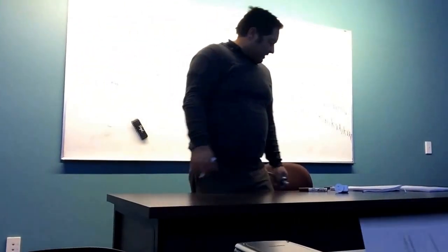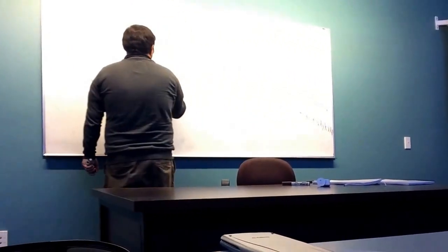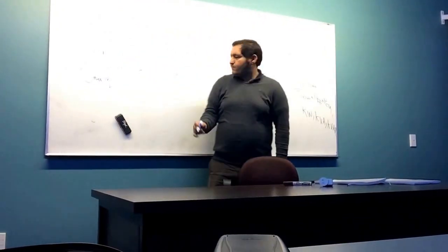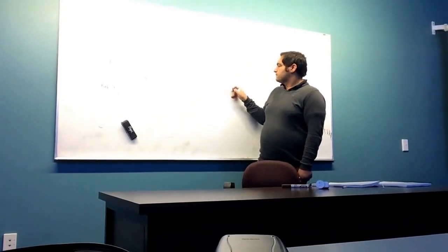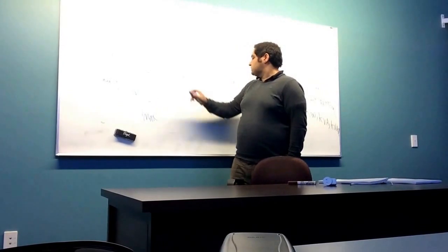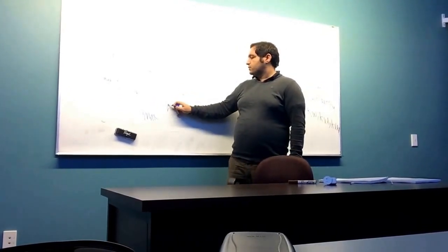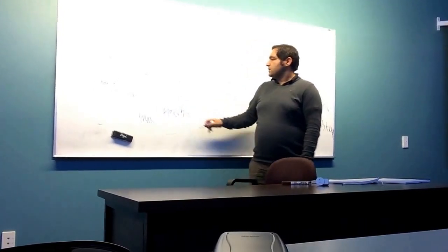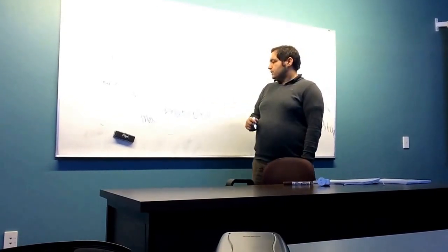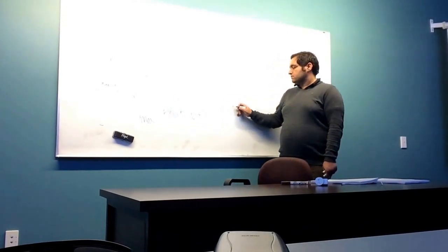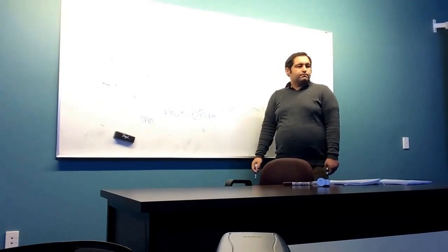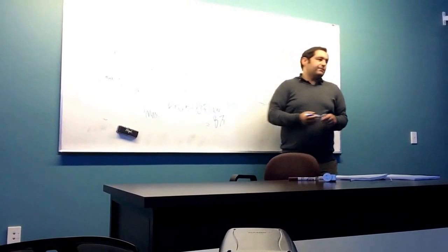So the load for maximum efficiency equals 0.56 times the full load capacity of the transformer, 250 kilovolt ampere, which equals 140 kilovolt ampere. Now, efficiency max equals output 140 kilovolt ampere over 140 kilovolt ampere plus these two, 5 plus 16, times 100%, which equals 87%. Is it clear, Ahmad?